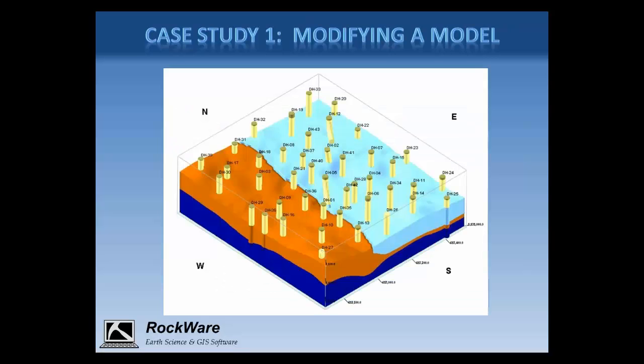Now that I've gone through this process, I can regenerate the stratigraphy model through the Stratigraphy menu in the Borehole Manager to create the model displayed here. You can see that the unit is now limited to areas just within the polygon that I drew to define the extents of the unit. Now I'd like to switch over to the RockWorks program and go through these steps just within the interface.